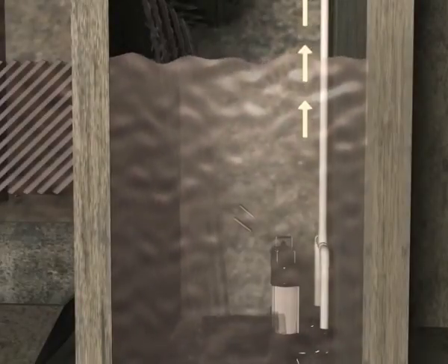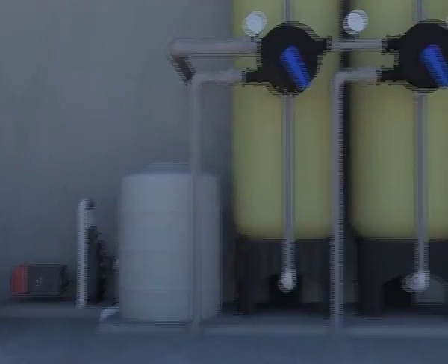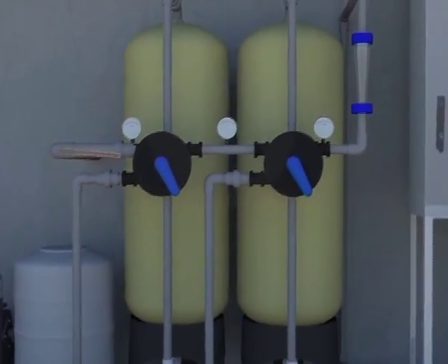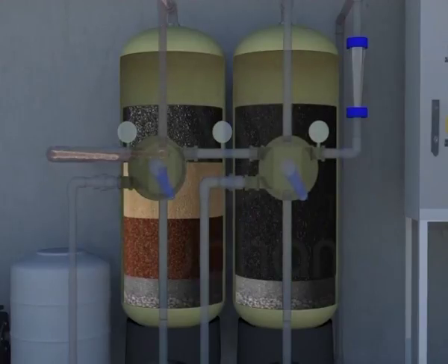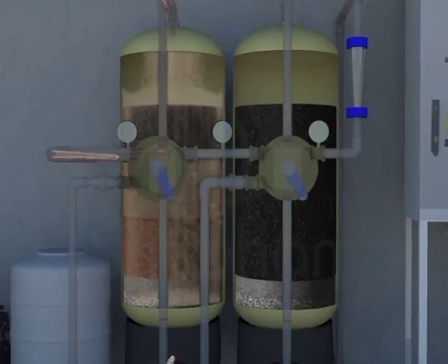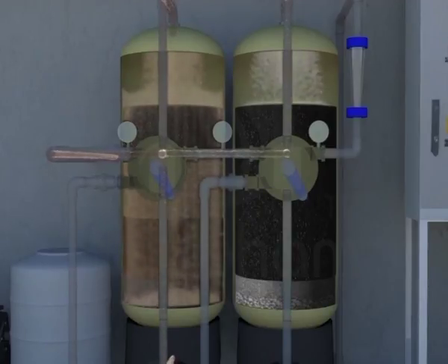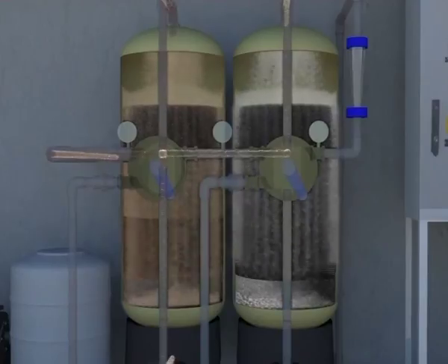After the biological step, treated water can be further polished by means of specific tertiary treatments such as the use of membranes, for example microfiltration, ultrafiltration and reverse osmosis, or other chemical physical processes such as activated carbon, precipitation, chelation for the removal of specific pollutants and to further improve water characteristics. The last process is land disposal of wastewaters.